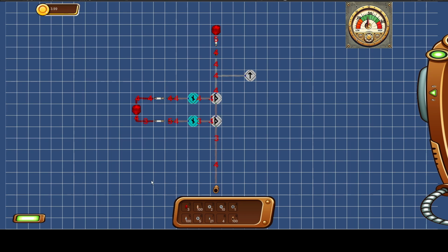So I modified that one a little bit. Here you'll see this is a NAND gate. Similar to how we had that inverter, all we've done is add an additional transistor right here. When this is off, power goes to this output and doesn't shunt to ground. Similarly, if only one of them is on, not much of a problem. Actually, that one moving was probably fine because power does run that way.